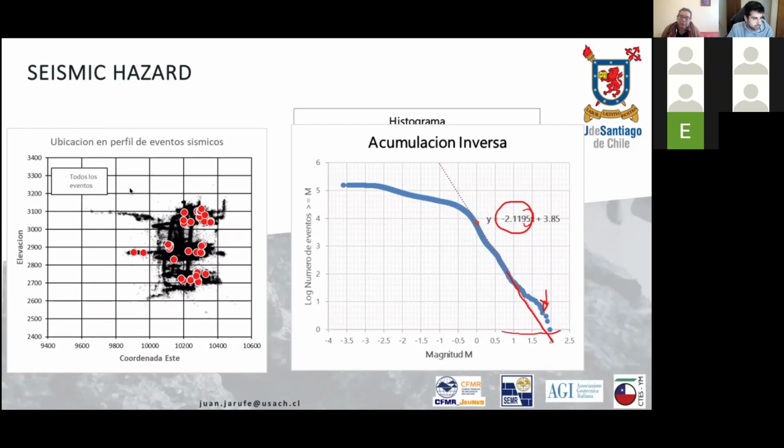He was asking about data management to create these models, and I was mentioning that you need to have good quality data about your mine sequence, or if you have a tunnel, how you are advancing your tunnel, so you can create models that are representative of the real excavations you are making, and that way you can find better correlations between your model and your seismicity.